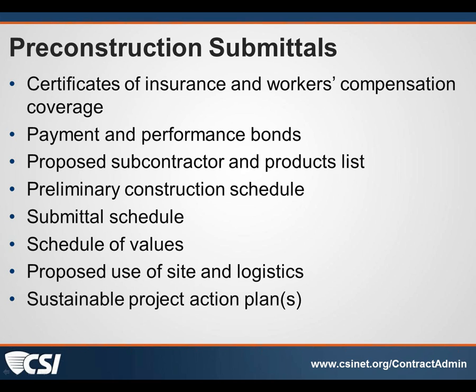There's a schedule of values that we want to see, to start to see how the construction contract is broken down. Certainly we want to have information there that is followable. On my projects, I try to encourage folks that more information is better. I don't mind going through a lot of pages because it allows me greater detail and a better ability to see what's in place and to, as I'm required to do, end up in the end to certify that application for payment. So getting a schedule of values and the way that they're going to break those applications down is another one of the pre-construction submittals.